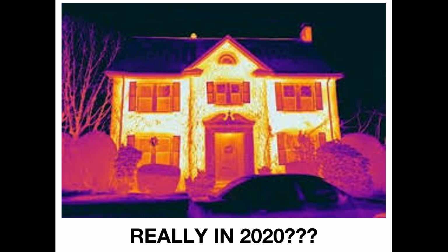And this is a fairly recent thermal image of a new build property, and that's the kind of heat loss that you're seeing through that building. Anybody that's not done heat loss, you can see that these purple bits are cooler than these other bits. This is quite warm in comparison. So the face of this wall, you can see the roof looks like it's fairly well insulated, but there's issues on the walls here. Okay, and that's what we're getting because there isn't the performance testing.